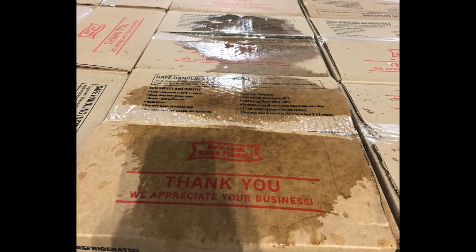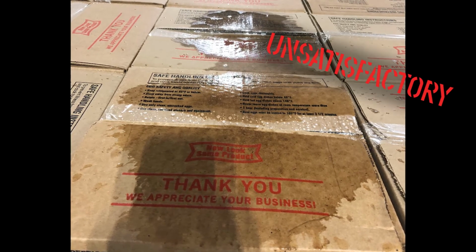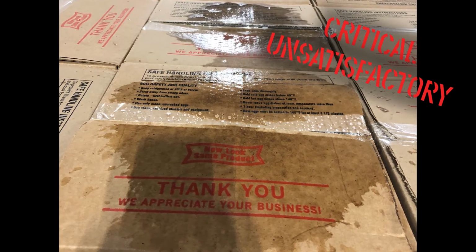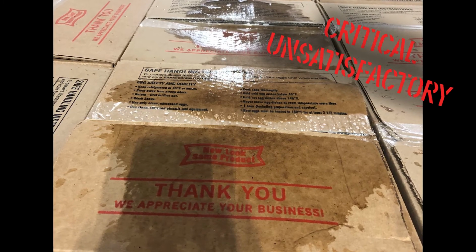This is an example of condensation forming on the ceiling of a cooler, likely due to ambient humidity or temperature differentials between the cooler and the exterior of the facility. While the cause of the condensation is a maintenance issue, the routine cleaning of the surface is a sanitation concern. If not addressed, this condition will lead to microbial growth or could drip directly onto finished product. This is an unsatisfactory finding in a critical area and must be addressed before this area of the cooler may be used.